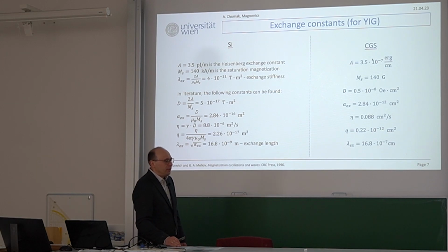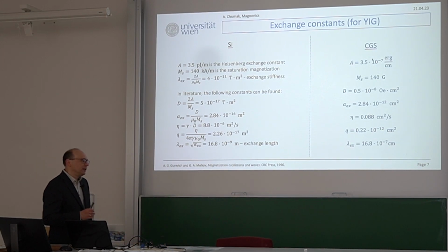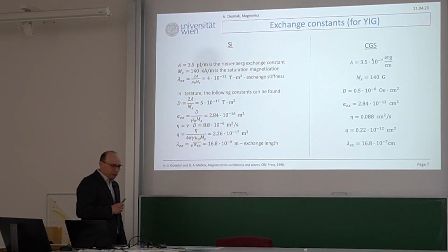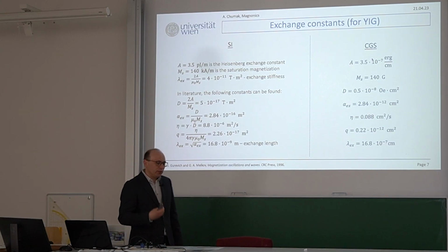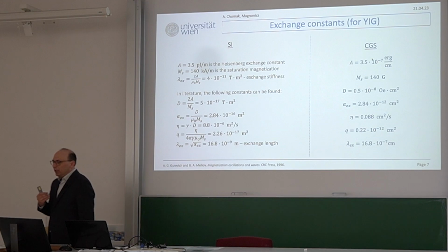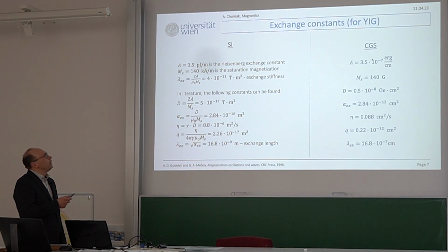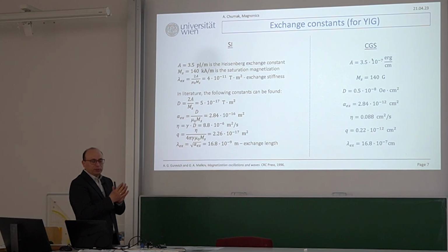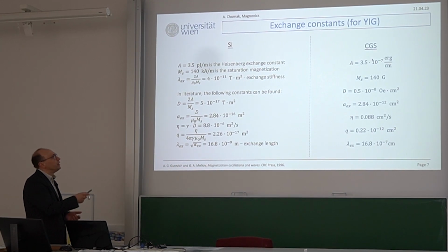For example, for spin wave dispersion, exchange stiffness pretty often is more important. That's why if you want to have a stronger contribution of exchange energy to your system, like we did in gallium doped YIG, you not necessarily have to search for a way to increase your A, but instead, if you decrease Ms, simply the saturation magnetization, your dispersion curves are getting much more exchange, and that's what really happens.